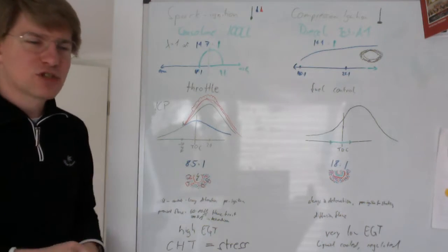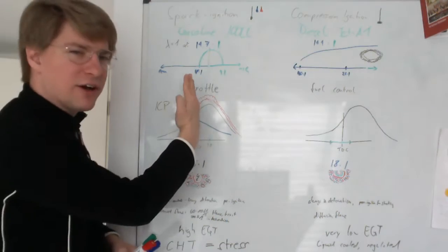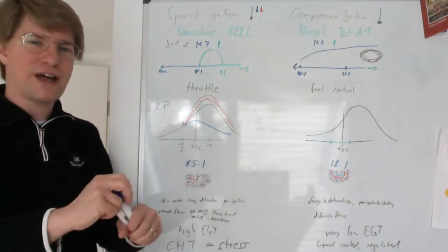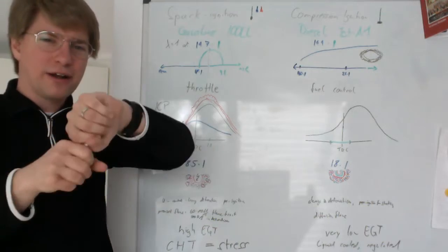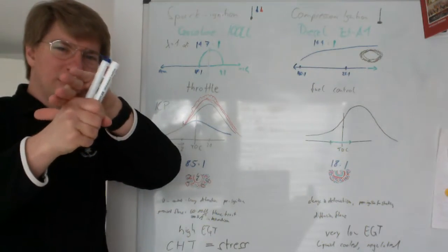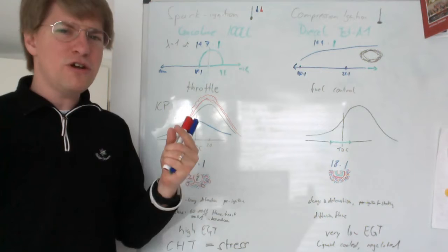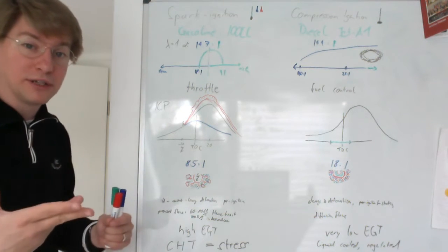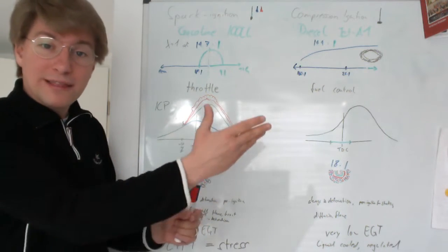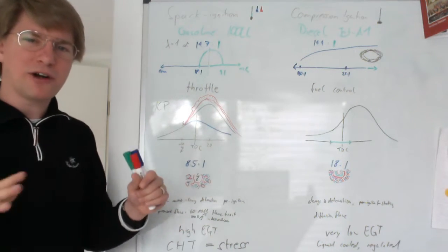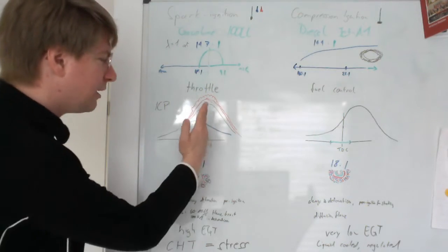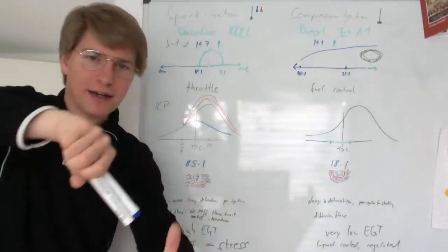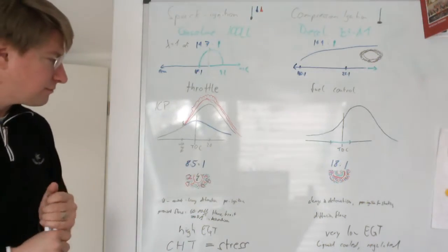this horrible squiggly line with the very high pressure, and also the very high pressure very close to the top dead center because everything happens so fast. So there's a lot of pressure going on, but the crank angle is still not far enough to do anything useful with it. And that's actually the reason why the best power output is not when the combustion is fastest, but the best power output is actually when the combustion is a little bit slower, because then we get the peak closer to the 20 degrees top dead center where we can really get work done.